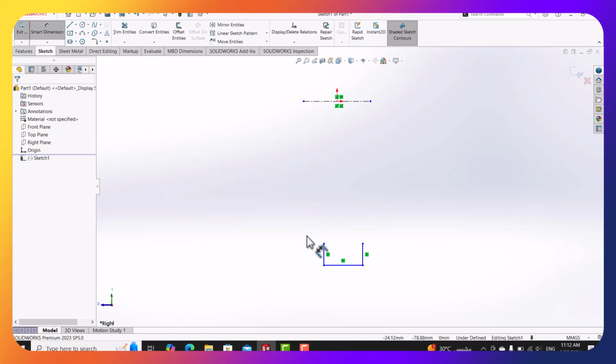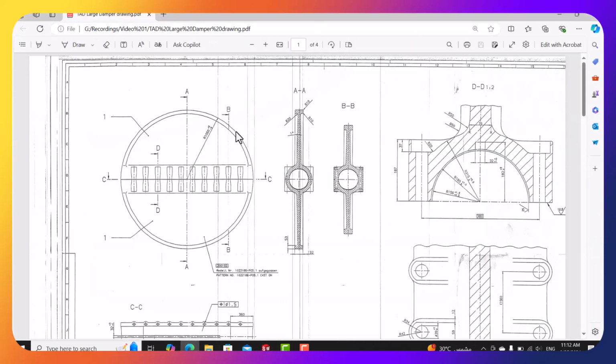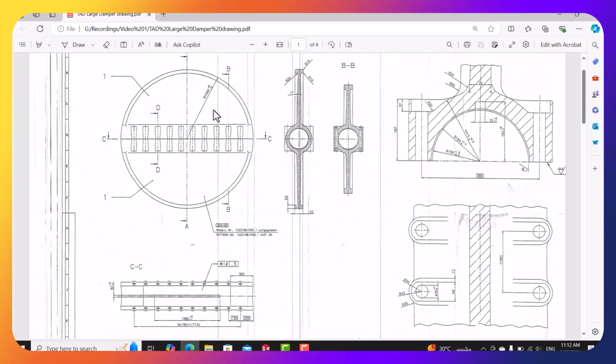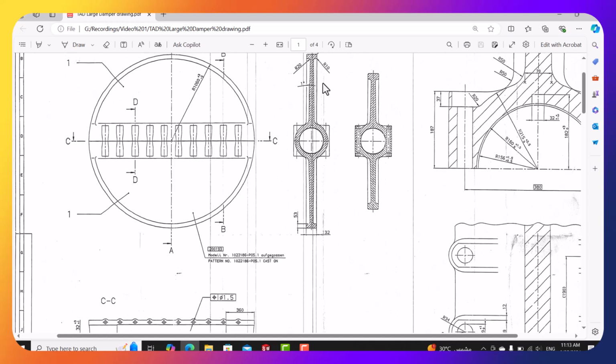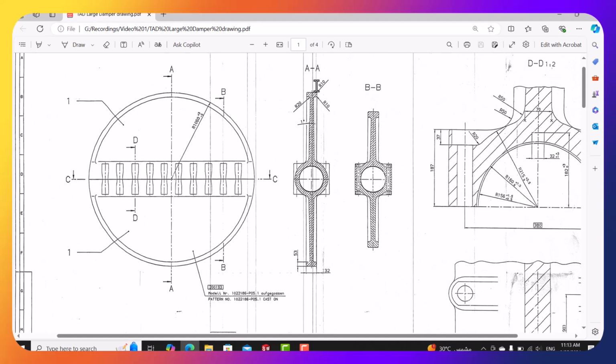Now we are heading to our drawing in order to read the views, to make the 3D model of this. If you look at this view, which we already called the elevation, we have the outer radius of 1060, which indicates that this model is a revolved model. We have R, which means this is a circle or something. And he gave us a section view here, AA. If we check it, we can make half of this drawing and simply revolve it.